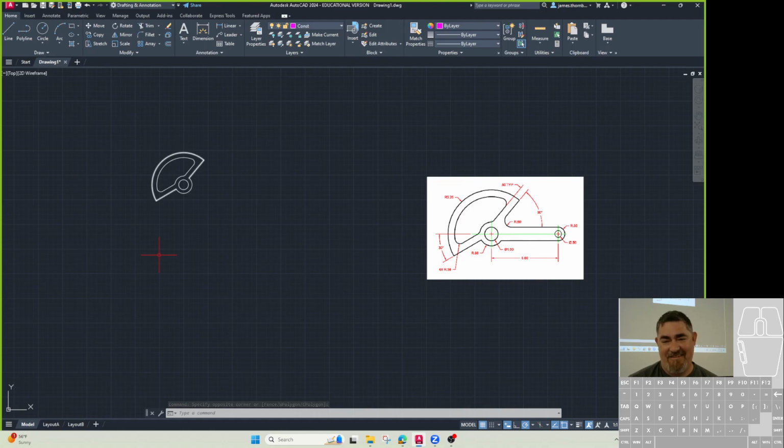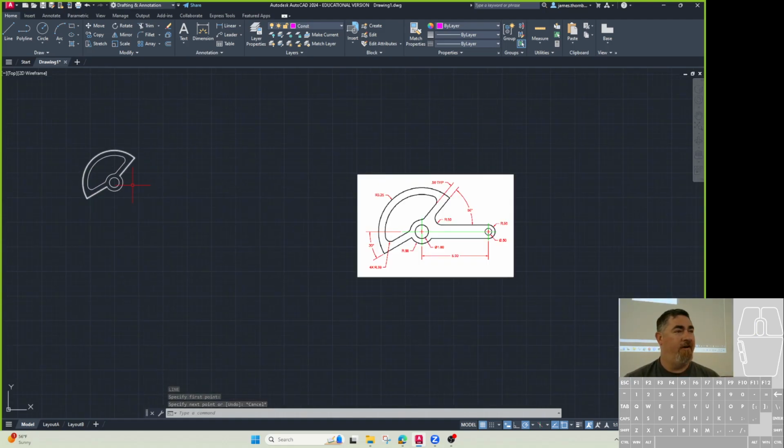I would draw a line from the center of that first circle we did over, what, 5 inches the same? Yep. So I could draw a line from the center here over 5, and then draw circles. That works. I'm trying to reduce the amount of things I'm drawing. There's always multiple ways to do things. One is you can draw extra lines, use that, and then delete it or trim it. Other ways you can use the tracking to try and get there without drawing extra stuff.